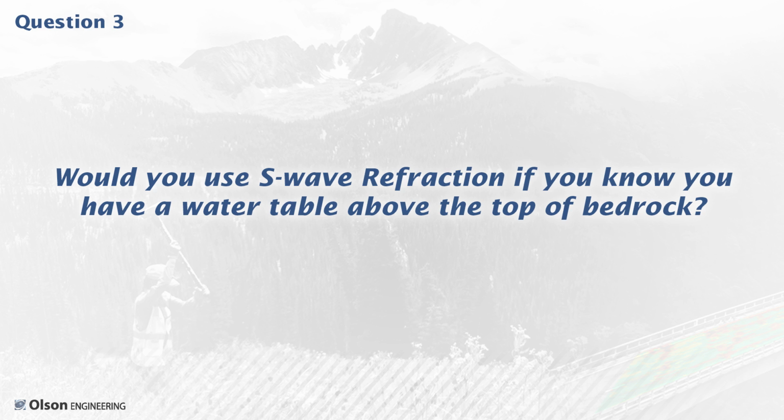Yeah, you could use S-wave refraction if you know you have a water table above the top of bedrock. This is a situation where I would recommend MASW over refraction tomography. And I can't remember where I was going with that.